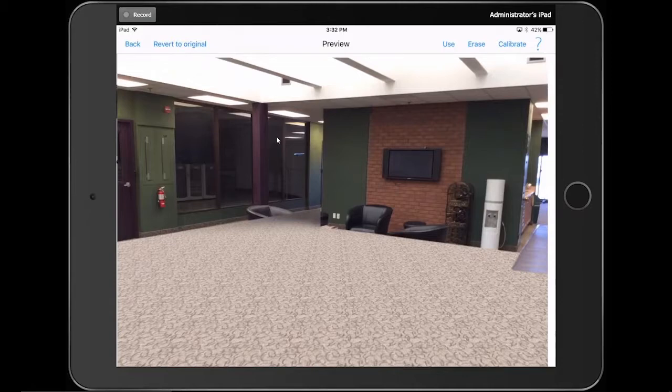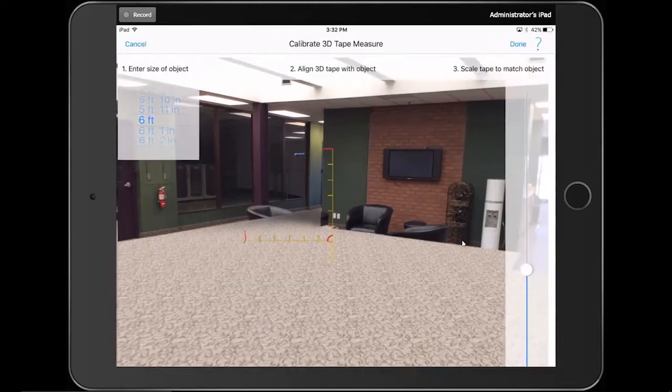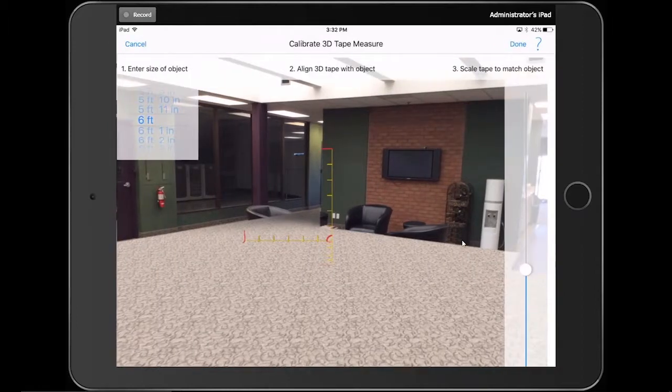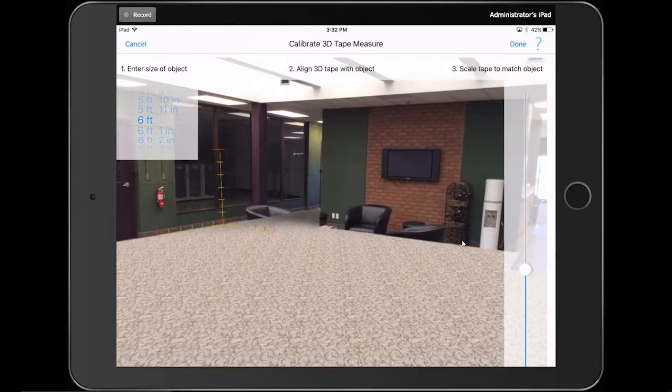Now, it may not actually fit the scene. This may not be the right photo to use, but you can see we've done the same thing where we've done a cleanup. We removed the verticals, and we've erased the floor. So what I'm going to do now is calibrate that, and I'm going to make sure that I bring my measuring tape over here, follow the same perspective lines, find 9 feet, and then scale it accordingly.